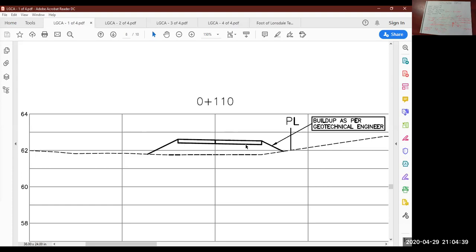You'll come across, go up, down this slope, and then the bottom of your area calculation is the dashed line. The dashed line is the original ground surface. So the amount of fill that's required at this station is this area. You'll calculate that in square meters.